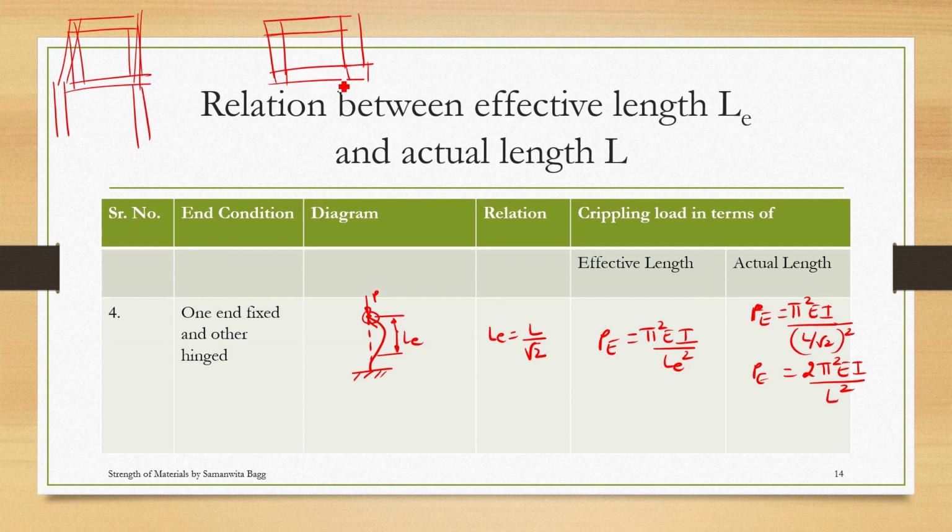These are the two ends wherein you get some load and also some amount of support from the floor below and some load from above on it. So this is the portion on which you can say that your load is being applied. This is actually the length in between on which your load is applied. It is not applied on this entire length of the column which is built. And this height of the column which you generally have for your houses is approximately 9 feet to 12 feet depending on what height you want for your room.